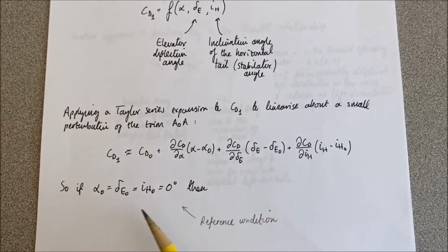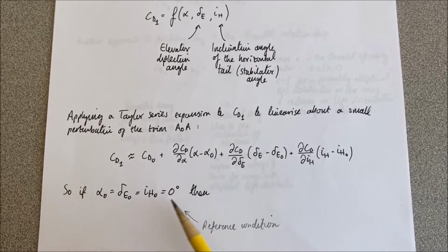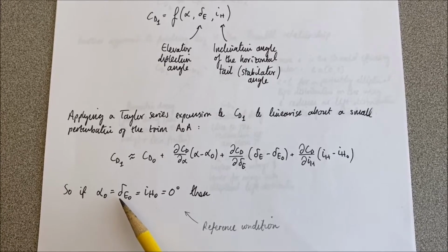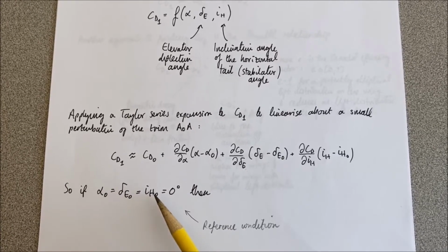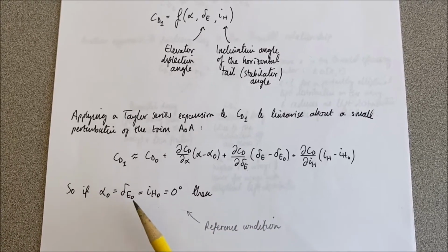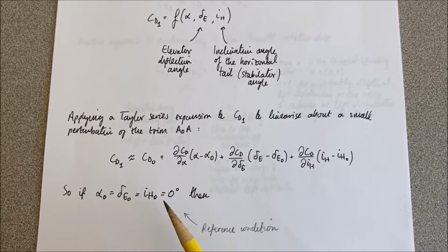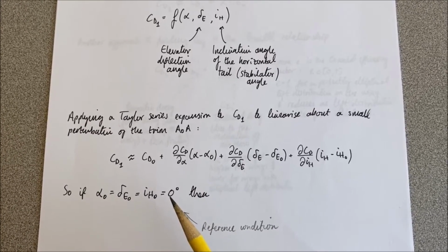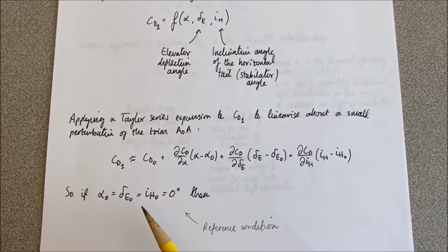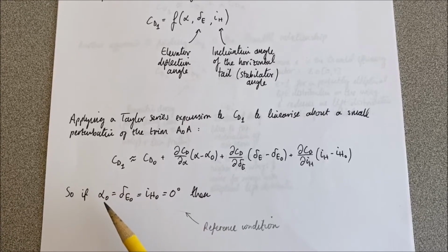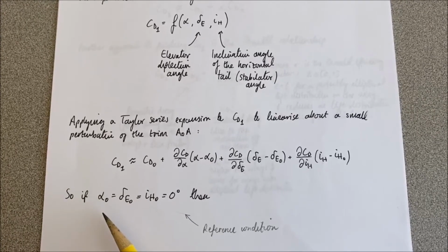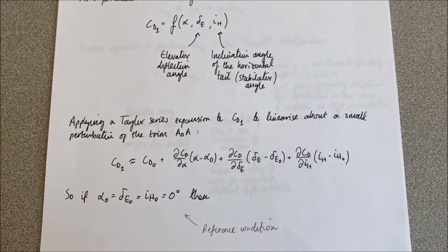And then we assume that this is our reference condition, so our reference condition is going to be alpha 0, delta subscript E0, and I subscript H0. What I mean by a reference condition is these terms may not actually be at 0 degrees with respect to the body axis system, but when we choose our trim condition, we set each of these equal to 0, and then we measure the changes in all of these angles with respect to that reference condition. Okay,